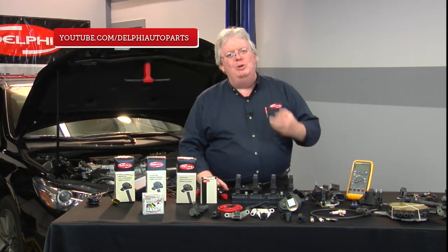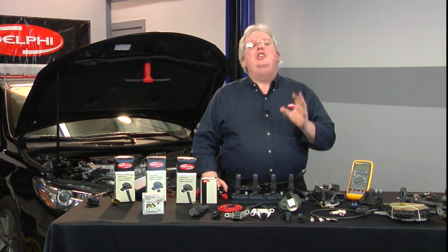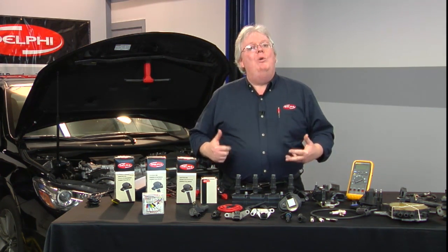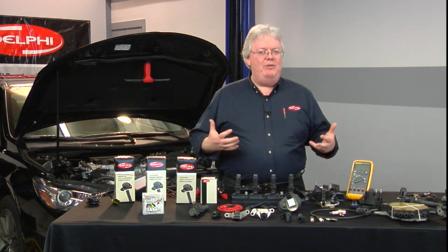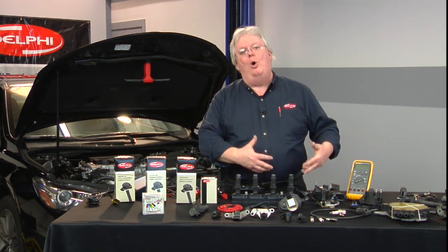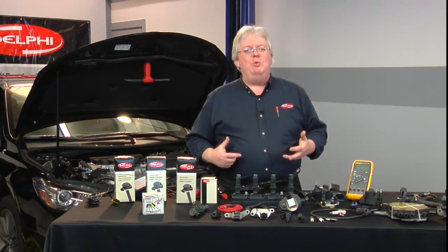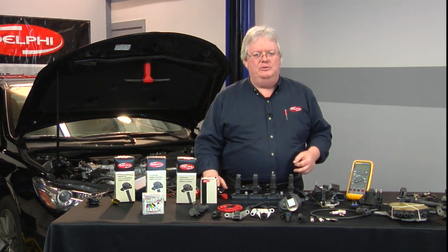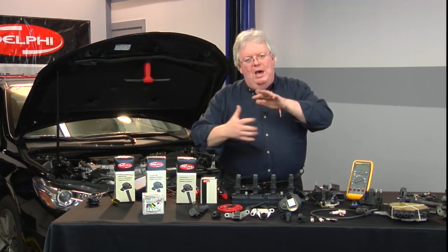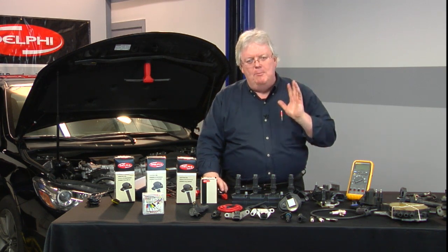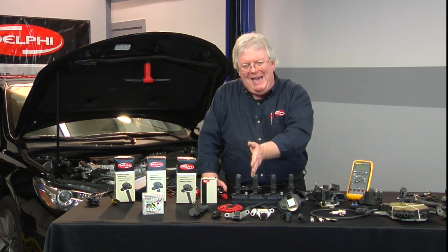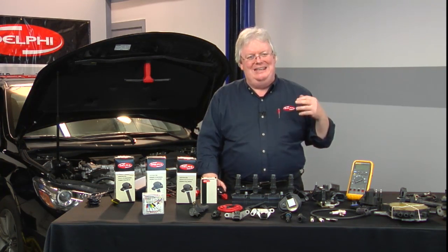If you're not a Mode 6 guru, you're not comfortable with it, you'll find it has a lot of extra help, especially with Ford misfires, because that's one of the Mode 6 parameters that is there on Fords. It'll help you a bunch with that, TID 53 or SID 80 on the newer CAN bus vehicles, knowing which component failed, at what level it failed, and so forth. So bone up on the Mode 6. That'll help you a bunch, definitively knowing how bad the cylinder is misfiring and which cylinder it is misfiring.